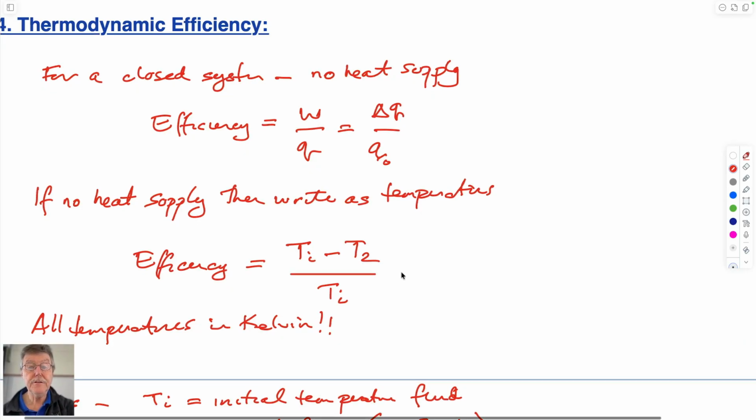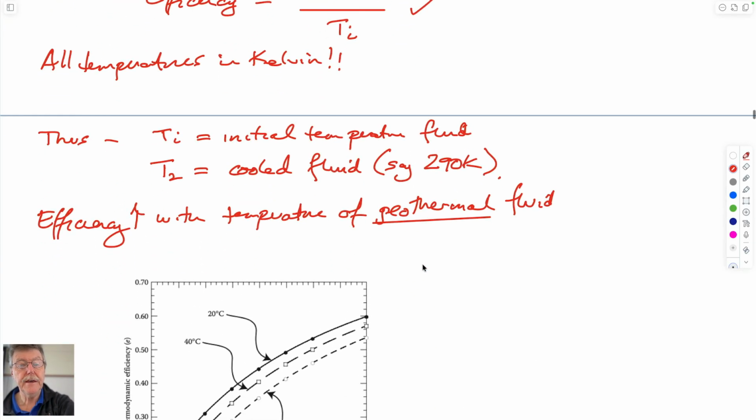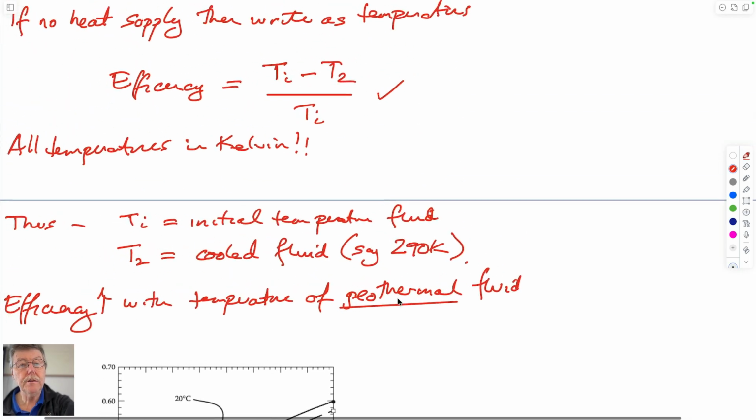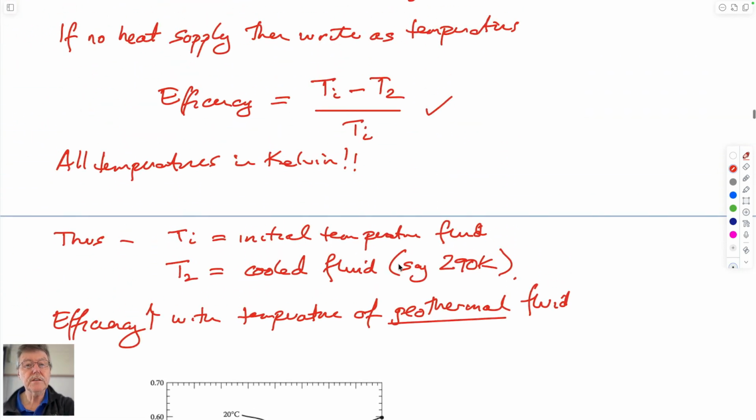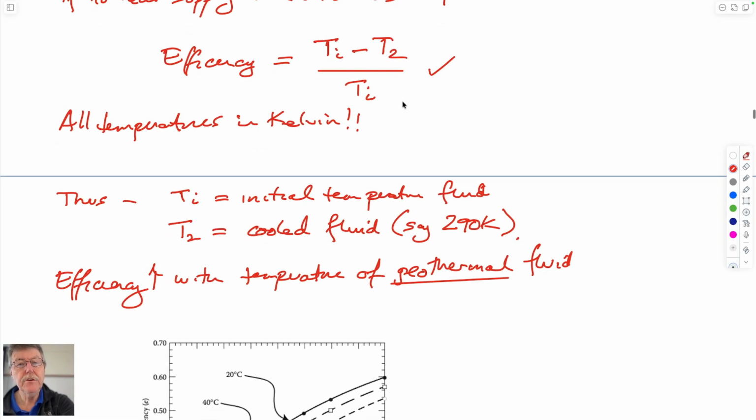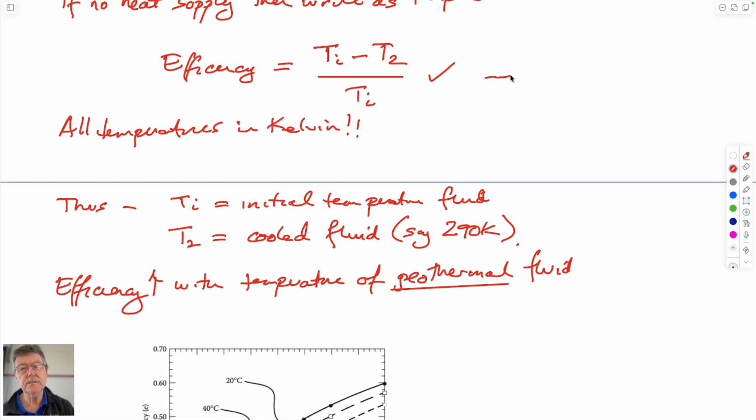We talked about thermodynamic efficiency. We did that twice. We talked about it today. If we plot thermodynamic efficiency, so if you worked out exactly what the initial state of the system was in going to a lower temperature, so this might be a geothermal reservoir at 100 degrees centigrade. You take the fluid out and it goes down to a background temperature of 20 degrees centigrade, which would be a normal ambient atmospheric average temperature. Then you can calculate exactly what this efficiency becomes. It's 1 minus delta T over